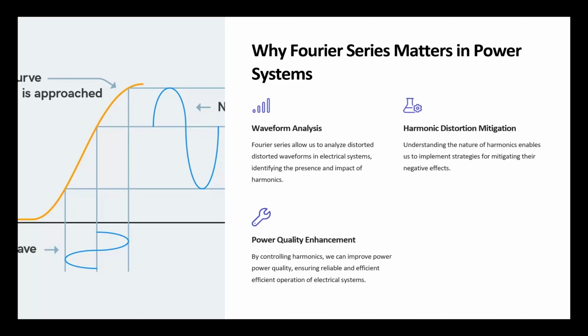Okay? Now, imagine if you give two waveforms at the same time to them, one is 60 hertz, another is 180. The third harmonic of 60 hertz. What's going to happen to the speed of that motor? It's going to go faster. It's not going to go faster precisely, okay?